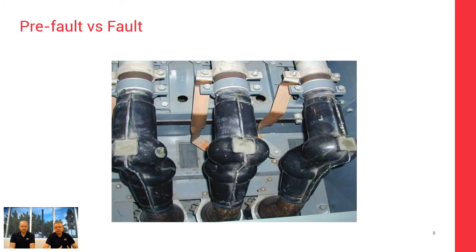So if we find that, we've taken the time to do a condition survey, we've seen that something's discharging, then we've got to take a bit of a leap of faith to take that off the network, to open it up in order to do the investigation and fix that problem. So we need to take a bus bar outage. We're going to have to remove these shrouds, these connections. We're going to have replacement parts. That's obviously going to have a cost that we have to deal with.